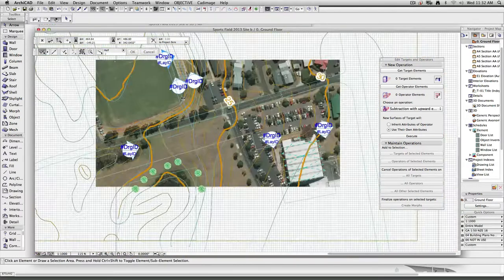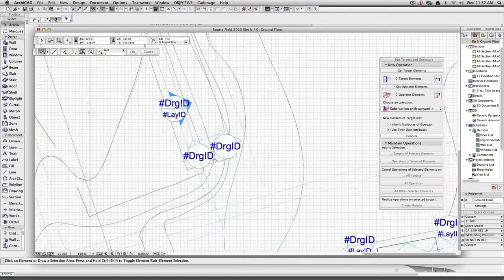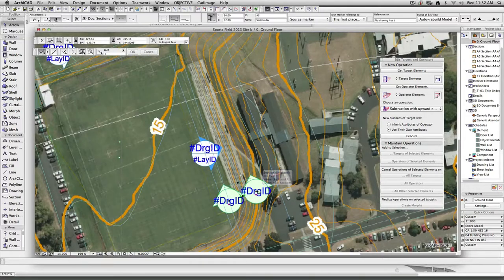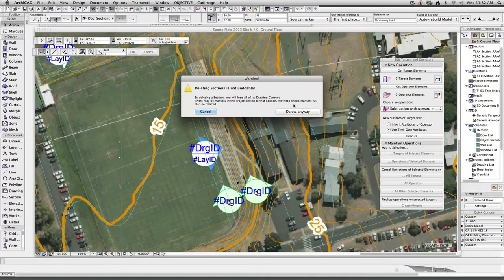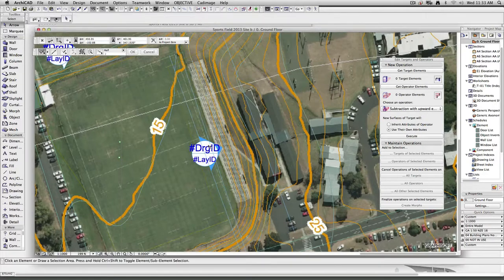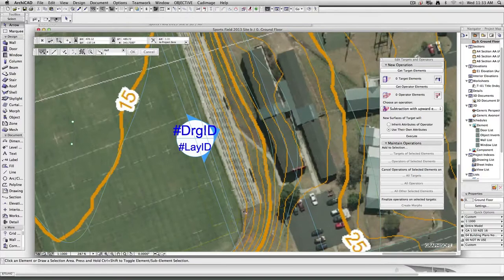Okay, so first we have to make sure that we can actually build our bleachers in here. What's important is that for bleachers, we want a nice even spacing of our contours going up the hill. If they're all evenly spaced, it means we've got a constant slope. You can see in the corner here, chances are that they're going to get buried a little bit, because all of a sudden the terrain's going out, so it's going to get higher. So we need those contours to be underneath our bleachers.